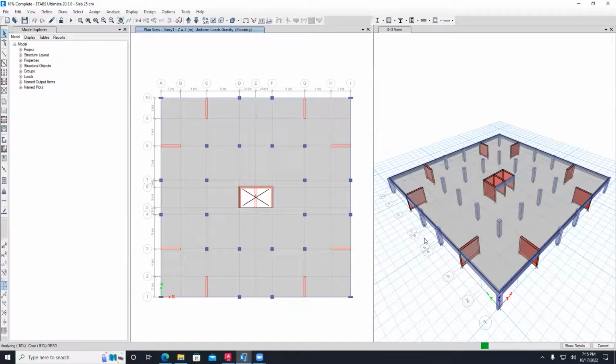It should be okay. Let me tell you guys. When you work for a design firm, we do 2D models and 3D models. We only need 3D models for buildings to do lateral load analysis. You want to do wind and seismic analysis, or seismic analysis and seismic design. So that's why we need the whole building. But if you want to design the beams and the slabs, it is enough to do a 2D model.